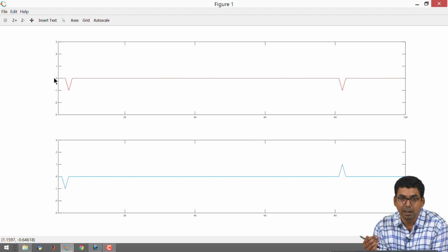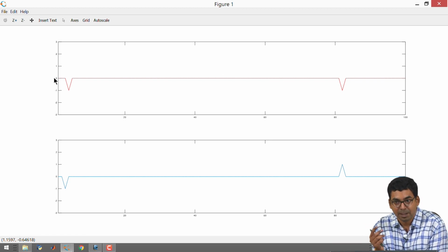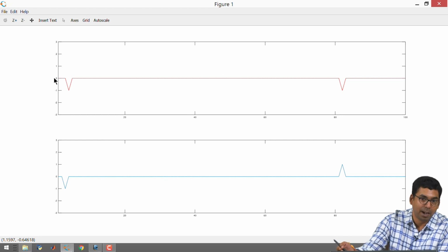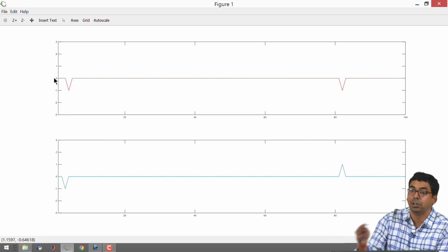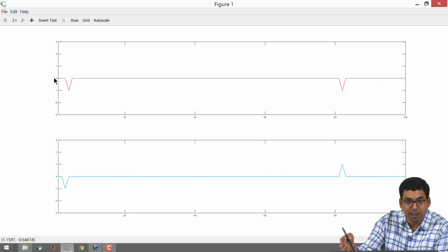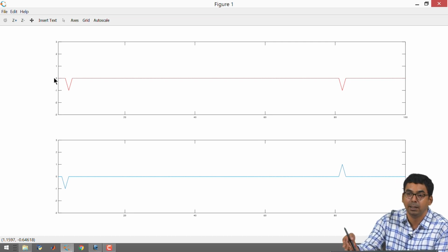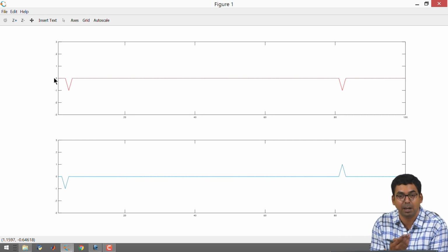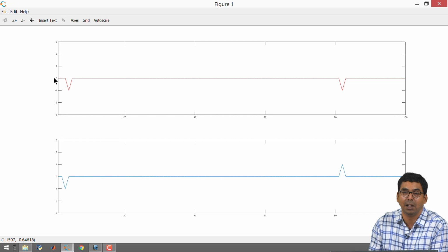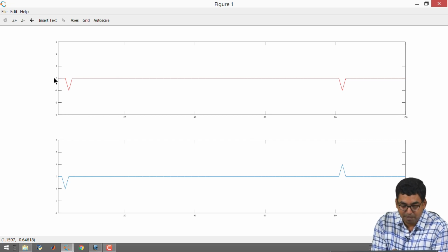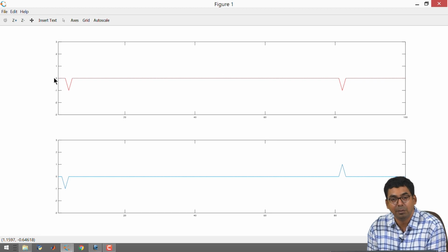On the right hand side the voltage actually flipped. If it flipped, your reflection coefficient was minus 1. Okay, that means on the right hand side you had a condition of RL very much less than RC, or you had a short circuit condition. Remember that we had two different boundary conditions for simulating this particular section of the transmission line. On the left hand side we have imposed one condition, on the right hand side we have imposed the opposite condition.